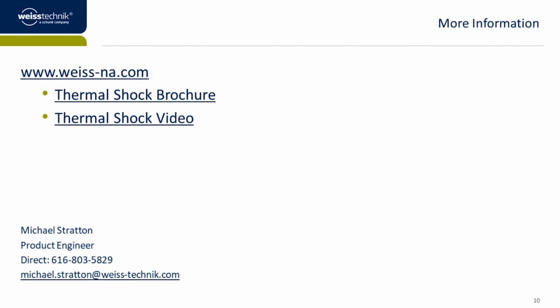Excellent. And just one last one, can you explain the traveling port again? I know you mentioned that in one of your slides, and there's a question, explain that traveling port, Michael. Yes. With the thermal shock chamber, we can't put ports in the windows, the doors, or anything like that because the basket moves from zone to zone. So instead, we have a port that's connected to the basket that leads to the outside of the test chamber, and you can use that traveling port to introduce your thermocouples or other temperature monitoring devices.